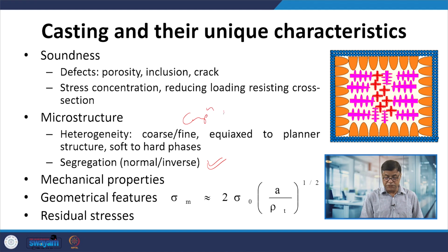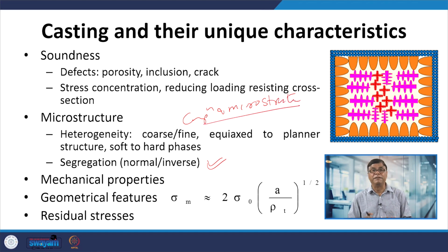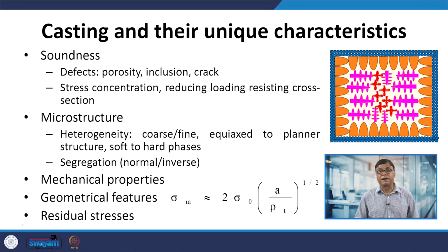If the composition and the microstructure are uniform, then the performance of the casting will be really excellent, but if there is heterogeneity or segregation tendency, then it will not just lead to compositional variation, but also microstructural variation, and these in turn will lead to reduced performance of the casting, which as per the application may affect the mechanical performance, tribological performance or the corrosion performance.